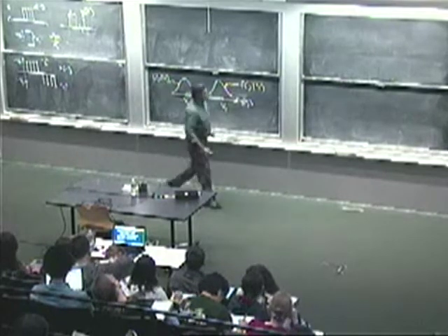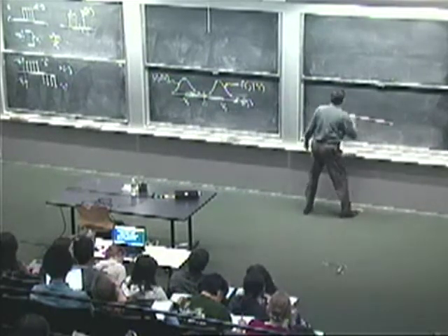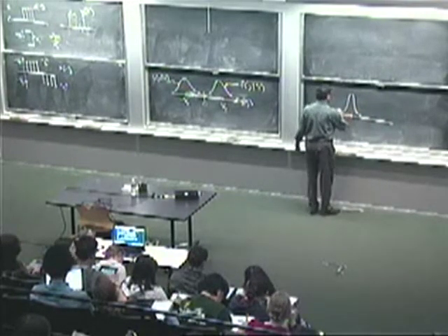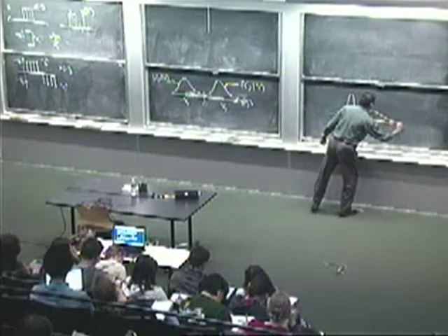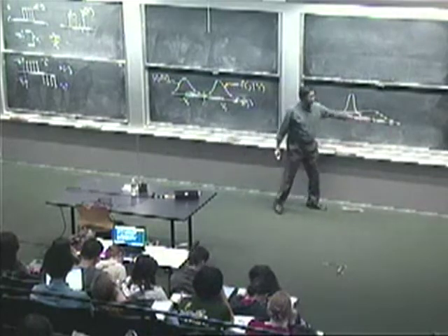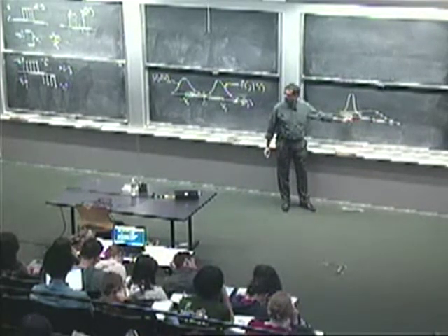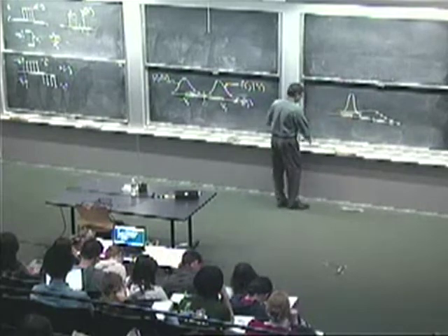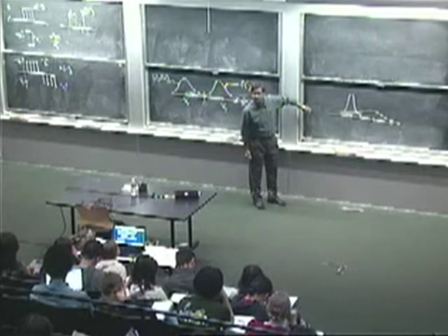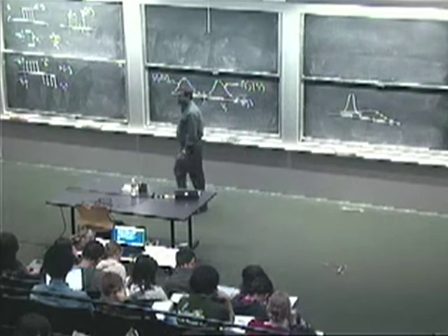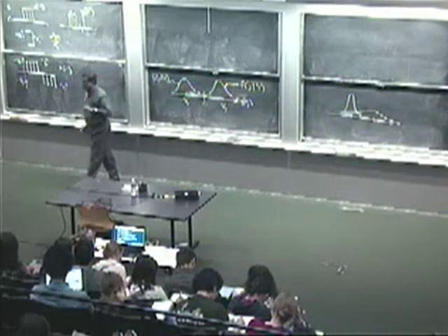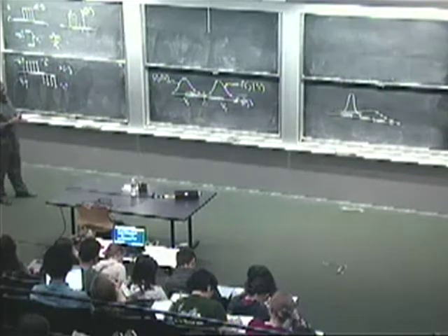Actually, you can imagine a picture, right, suppose the noise is very sharply peaked for one of these cases, and very shallow for the other one. Okay, so there's high variance for the ones, and there's low variance for the zeros. You might then anticipate that if you got a signal way over to the left here, you're going to call it a 1, not a 0. Okay, so each case needs to be dealt with separately. But assuming these are equal variance, which goes with the IID case, this is the optimum rule.